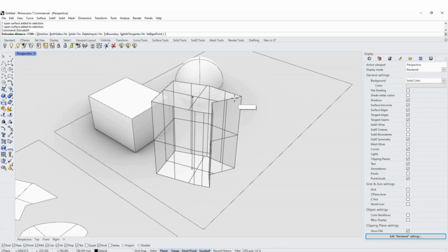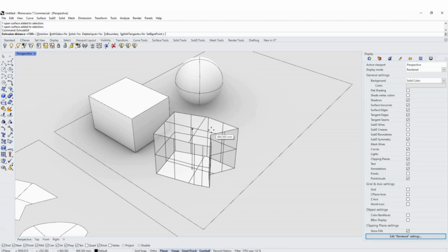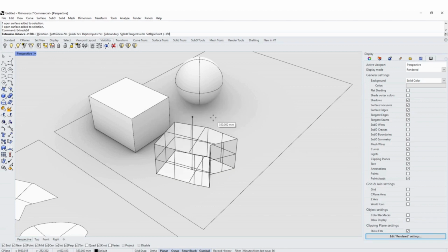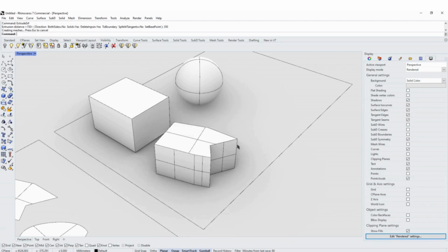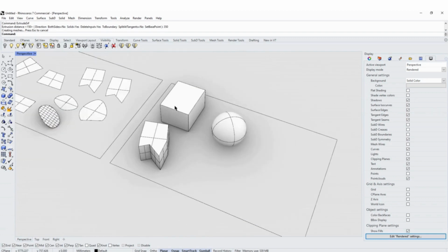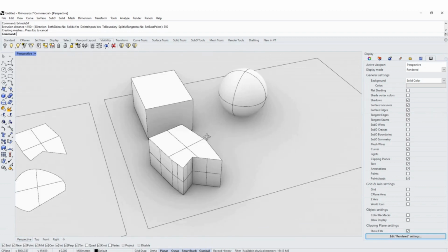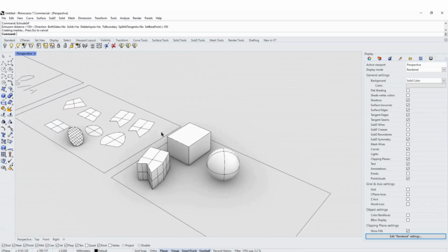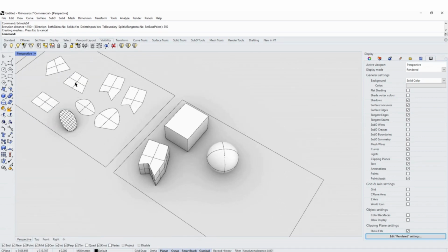And this is, you click Extrude Surface. You go and you click Extrude, and you can set the height. Let's say I want it 350 millimeters, and now you have, from a surface, you now just created a solid. The command, once again, is called Extrude Surface.